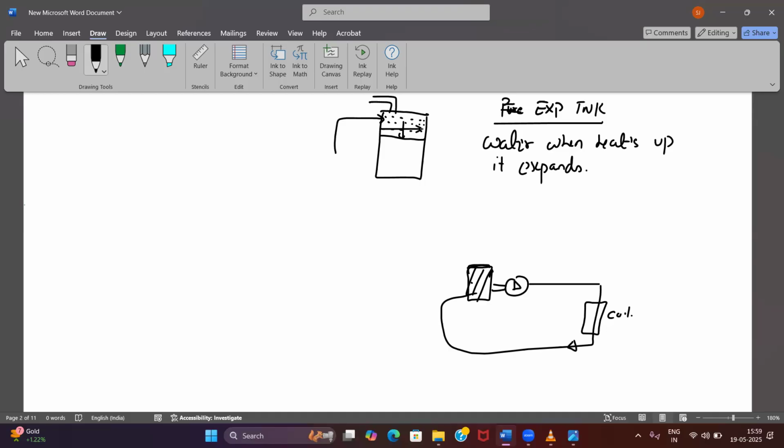Sir, this vent that is kept, it remains open, so the pressure that develops is released through it? Yes, the gases and this expansion will be released from here. Okay, the entrapped gases. You cannot seal the tank. If the tank is sealed, then there will be a time when the expansion will no longer be taken care of because the air pressure will increase. You have to vent it out.